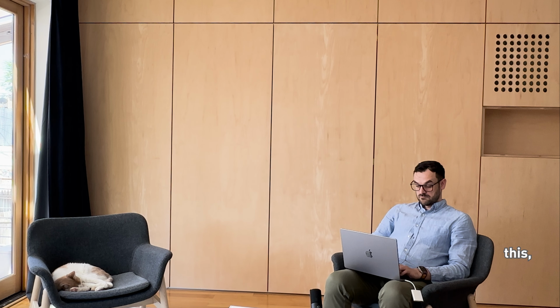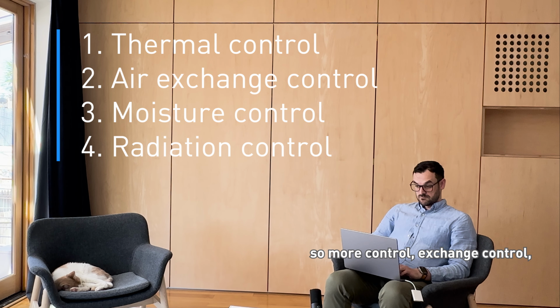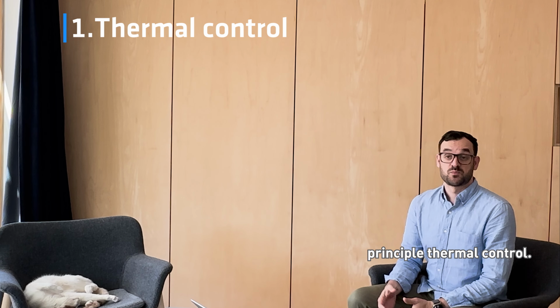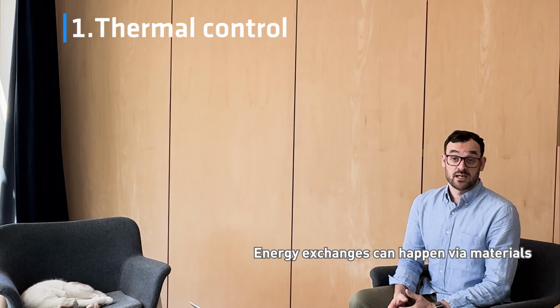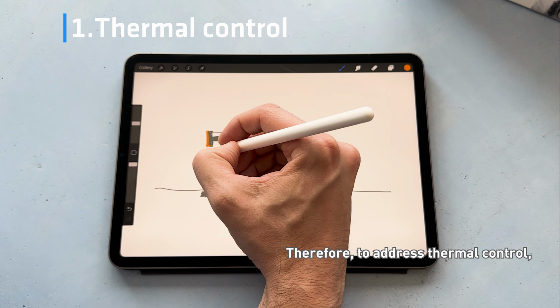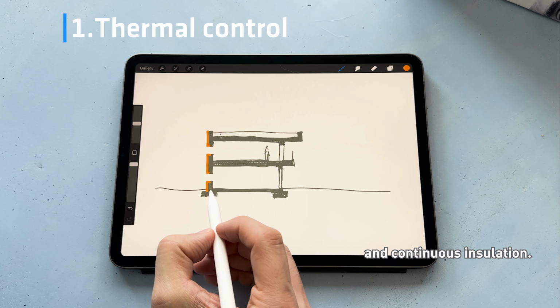To achieve this, passive house design can be broken down into 4 principles: thermal control, exchange control, moisture control, and radiation control. First, the most obvious principle: thermal control. Energy exchanges can happen via materials that are in contact with both the inside and the outside. Therefore, to address thermal control, passive house design prioritizes highly efficient and continuous insulation.